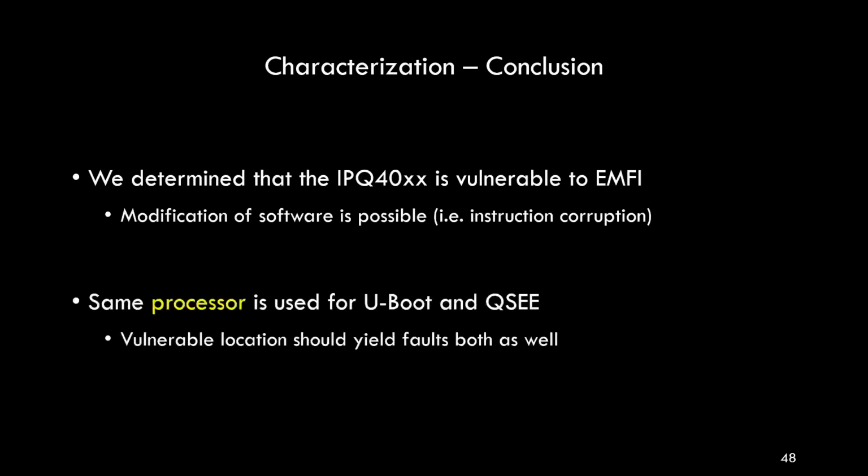An important observation to make is that the same processor is being used for executing the U-boot code and the QSEE code. The test program is executed in U-boot, but the hardware is exactly the same for executing the QSEE code, which is running at a completely different privilege. So if you are able to inject a glitch in U-boot, we are also probably able to inject one when QSEE code is being executed. So this vulnerable location should yield faults in both environments.